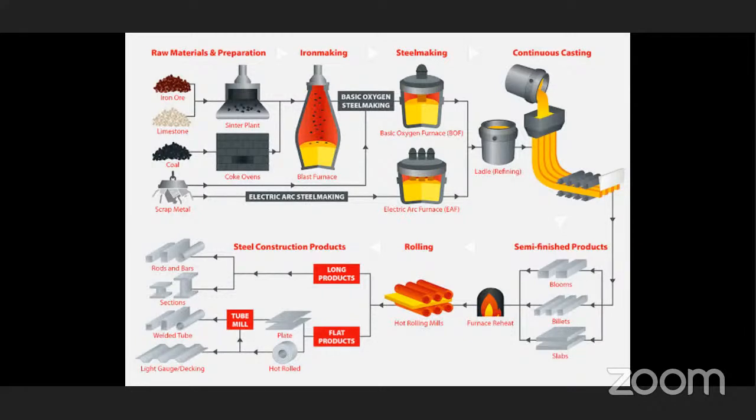How many kinds of steel making are there? Two types. One is acid steel making and the next one is basic steel making. In acid steel making we use pig iron, and if it is low in sulfur and phosphorus, then the acid process is used, and the slag is required to retain only the silica and manganese oxide.